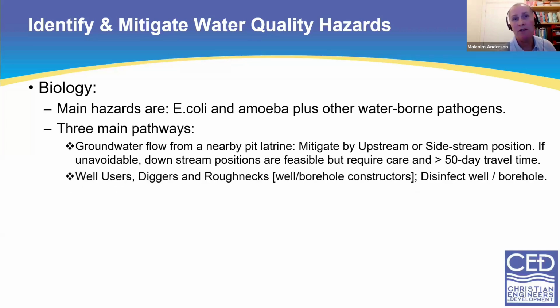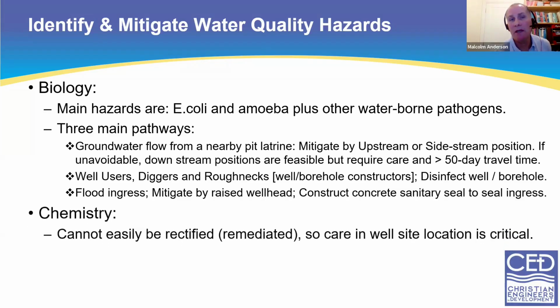As I said, the well users, diggers and roughnecks will contaminate the boreholes when they're first constructed. So disinfection is important after construction. And the other thing to take into account is flood ingress into the top of the well or borehole, and that's mitigated by having an appropriate concrete sanitary seal to prevent that water ingress.